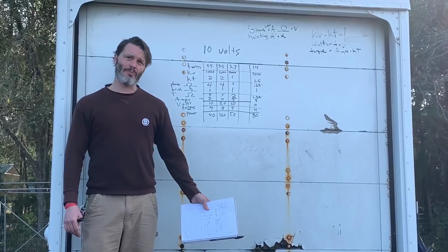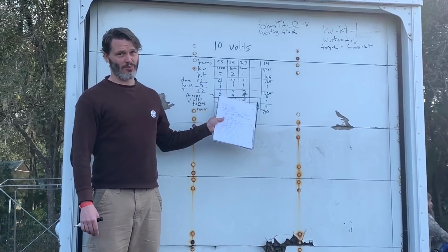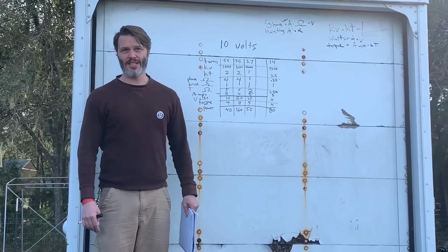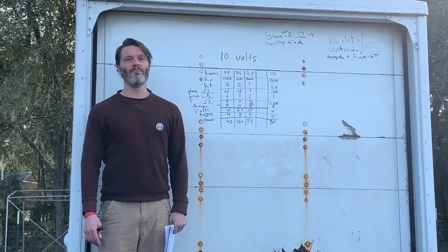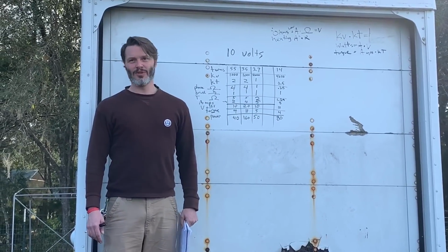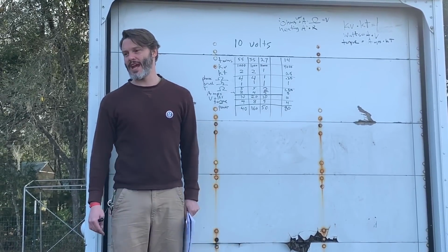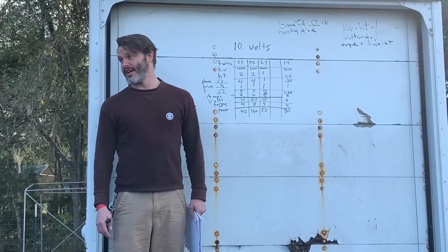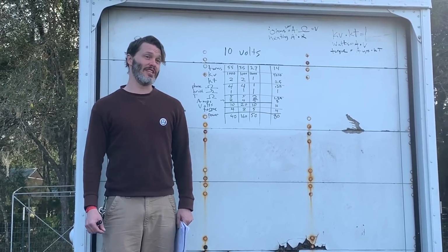So like on a Cabra, if I'm going to install a brush motor into it, I'm not going to install a really fast brush motor into it because it just doesn't have enough gear down to support it. So if I put a 14 turn in there, man, it's going to smoke immediately. If I put a 27 turn in there, it's not going to really be that happy. But if I bring it down to a 35 turn, it's not going to pull so many amps that it's going to smoke right away. And that's kind of the downside. That's the caveat to all this, is you've got to have enough gear down to deal with it.